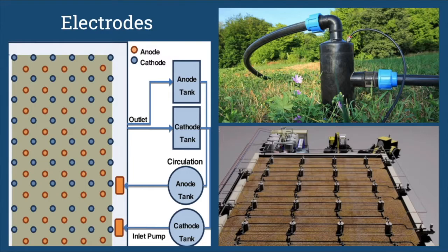The electrodes are typically installed in two parallel lines, one side with anodes and the other with cathodes, that are installed outside of the contaminated area to be treated. The electrodes can consist of either horizontal plates and pipes, or vertical pile sheets and pipes. Usually, raw materials are shipped to the site and then modified based on site geology and the size and shape of the contaminant plume. Common electrode array materials are steel sheets for cathodes and graphite sheets for anodes. For optimum treatment, electrode rows should be approximately 30 feet long and about 30 feet apart from one another. The depth of installation is dictated by the thickness of the contaminant zone.